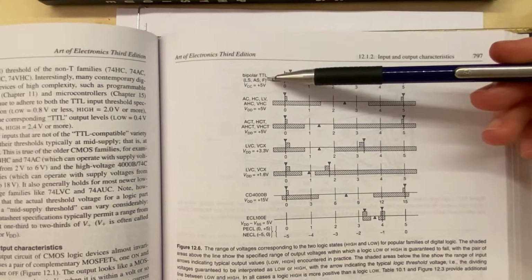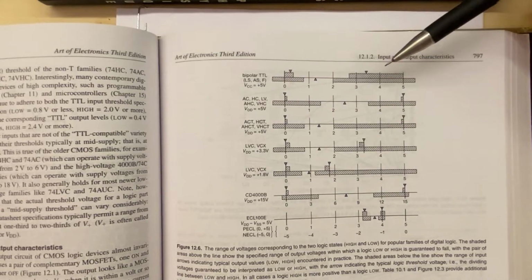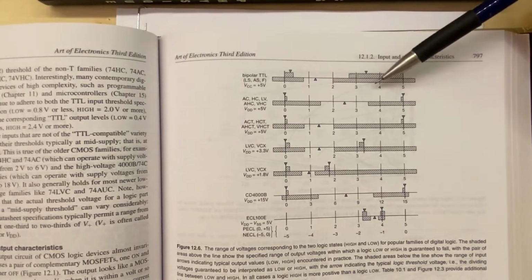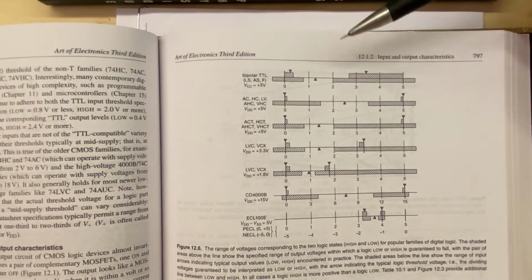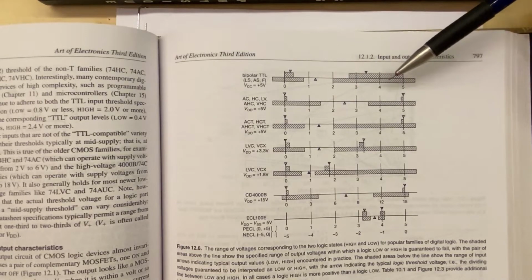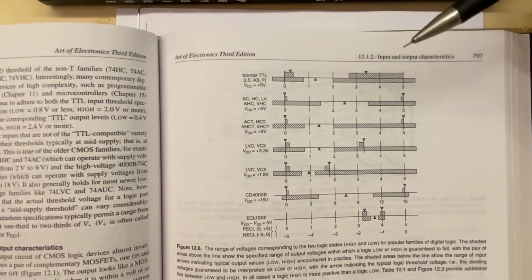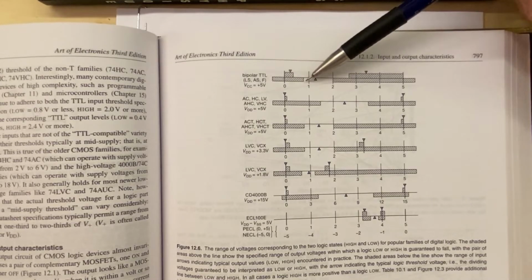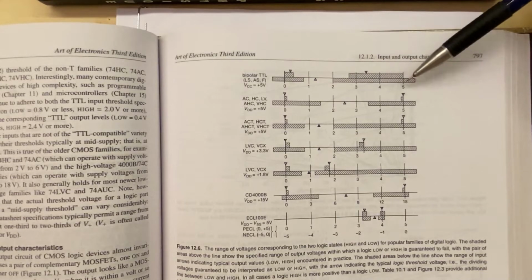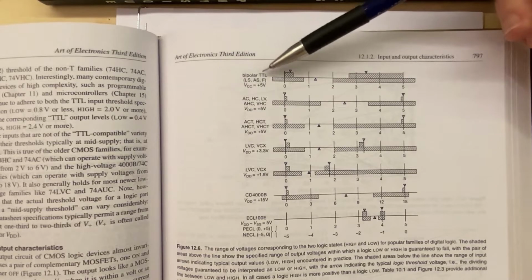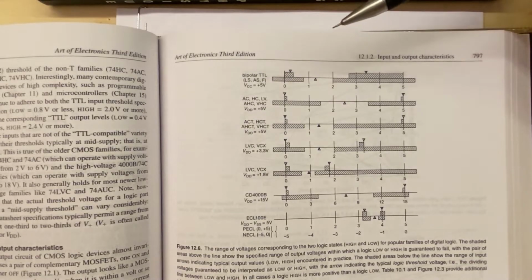The bipolar TTL was a famous and very popular one back in the day. And because it used BJTs, you can see the dividing line between high and low logic is not in the center, right? I mean, we go from 0 to 5 volts, and so you think a high would be from 2.5 to 5, and from 0 to 2.5 for a low. But in fact, the low is only from 0 to 0.8, whereas the high is from 2 to 5, and the midpoint is like 1.3 or something. And that just has to do with how the BJT works, like the voltage drop from the base emitter and stuff. But we won't get into that.